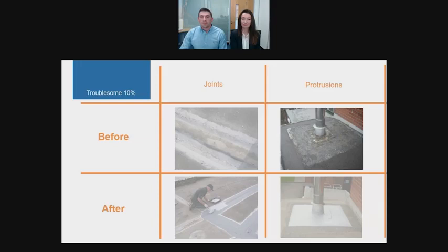The sealant used at metal penetration flashings eventually deteriorates with exposure, and it may not seal if the flashings have not been correctly cleaned before installation. They may also leak if the wrong diameter flashings have been used or the cover is not correctly installed. How to combat this? A flexible membrane that can adhere to different materials and be applied to complex geometries.